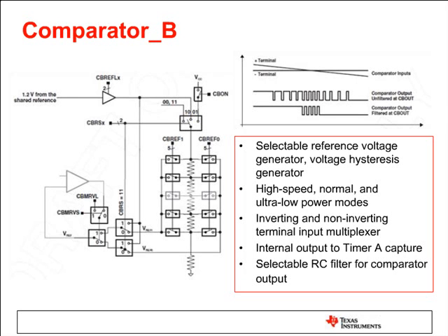And then you drop it down through a resistor ladder where you get to pick a high and a low reference into the comparator. And then you can automatically switch between those two once you've reached those thresholds. And you can do this all automatically without CPU intervention, which in the end adds up to power consumption.